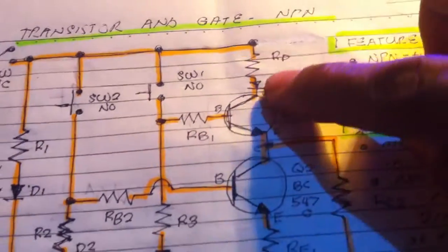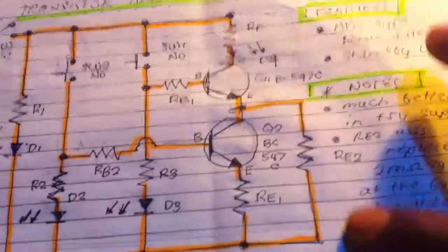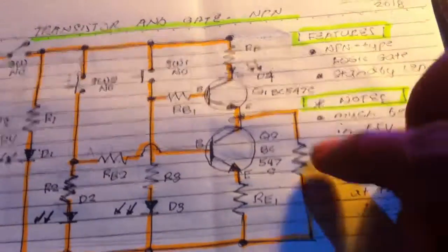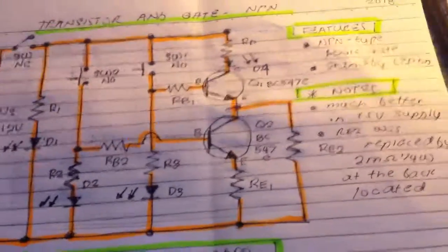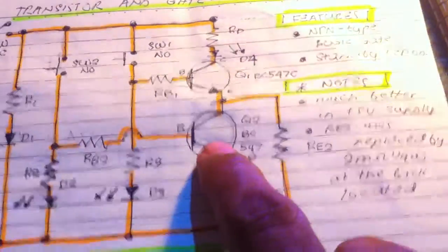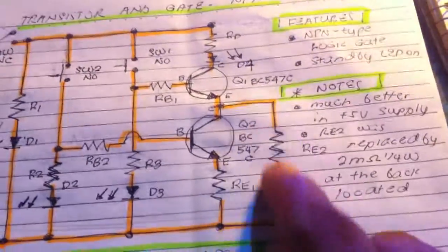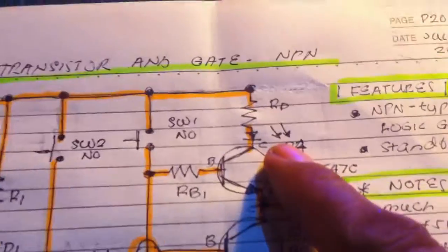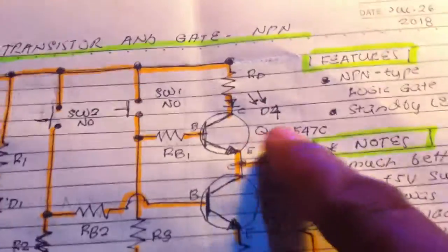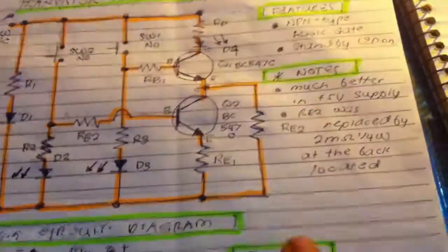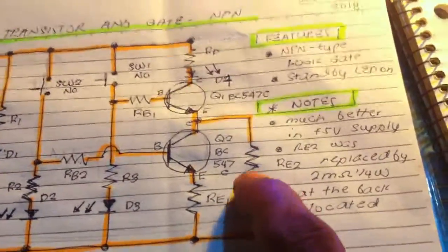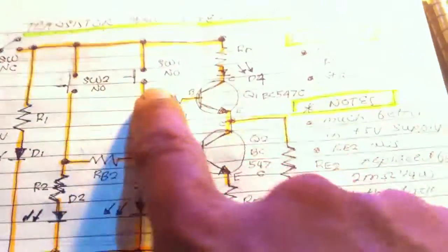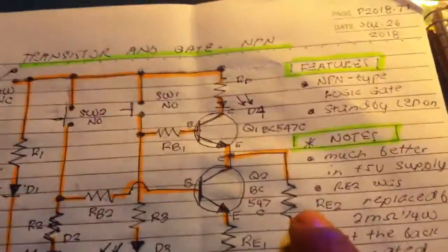When you push the button here, current flows here, to the collector only, and does not light the LED because the transistor is off, even without this resistor, because the LED current rating is 0.02, and there's a big resistance here making the LED turn off even though current flows here.